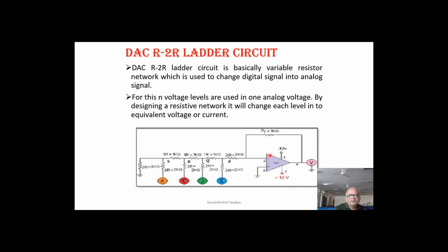So, this is an op amp. One leg of the op amp is connected to ground. So, we are applying different voltages in succession. This is a 4-bit thing. So we can start from 0 0 0 0, go up to 1 1 1 1, and accordingly 16 different voltages can be applied to this system, and this is a feedback resistor, and the output is available over here.